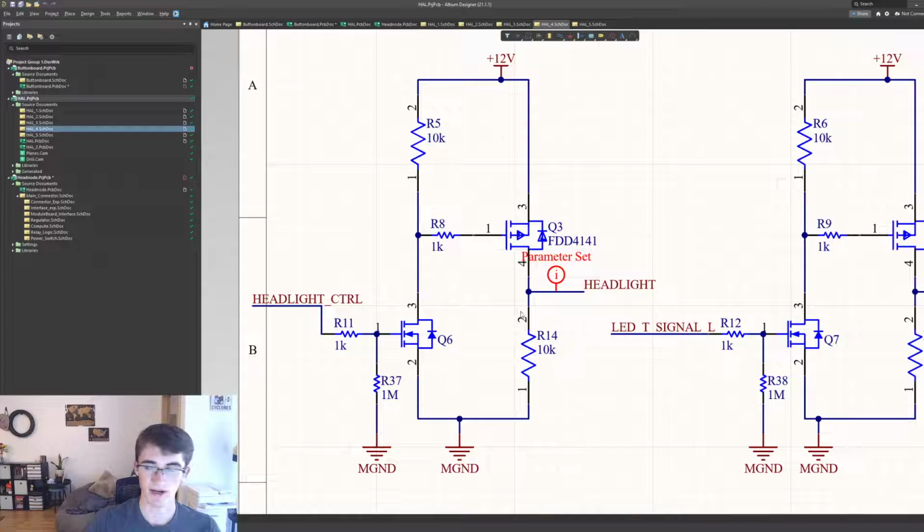It's just a basic MOSFET buffer with an NMOS and a PMOS, and they are spec'd high enough so that they can output at least up to like 5 or 10 amps. It's way over spec'd now. The reason for that is because when we first designed this board last year, we did not think about how much current the horn or the lights would draw.